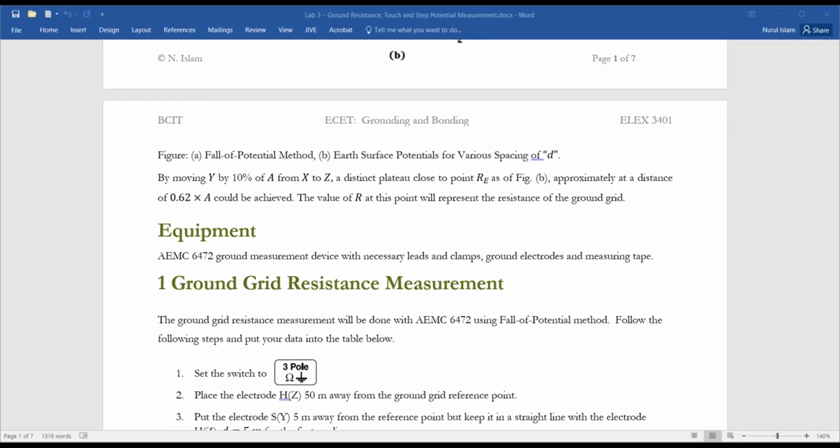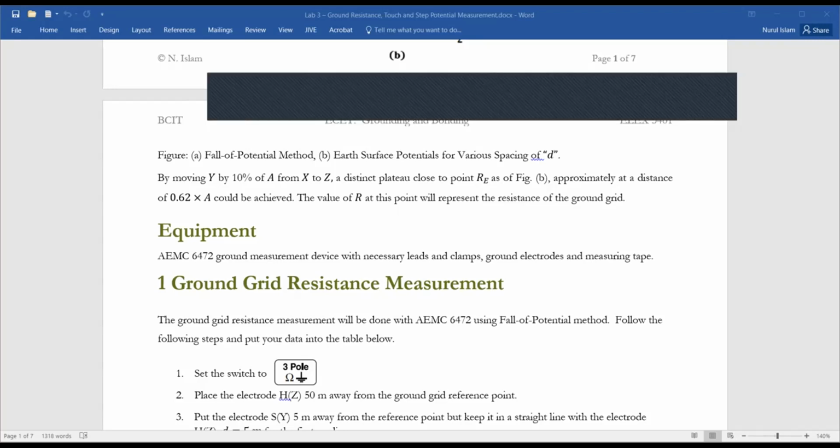See, the person is sitting in the car. This car is under voltage, but this person is safe because every metallic part of this car, or truck, will have the same voltage. All right, so yeah, you are right. Even shoe insulation doesn't stop the flow of current.